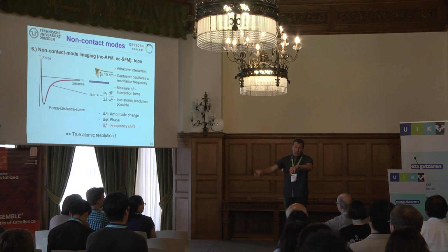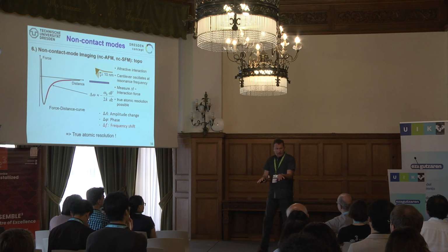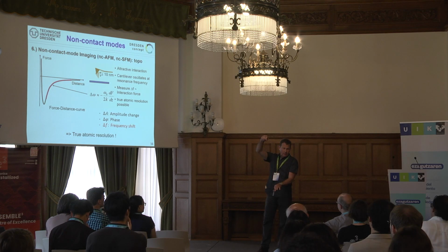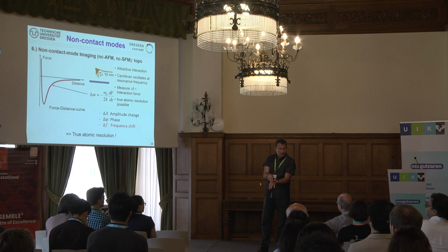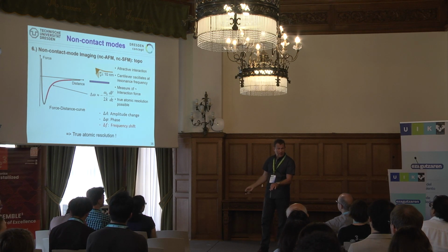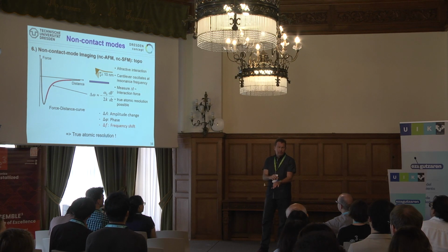Lithium niobate is one where you get an external compensation because there are not too many internal charges there. Now, if you go for vacuum, this is a huge potential, and one of the ways is to use Kelvin to really balance this off. So you go for electrostatic compensation on your cantilever here, we will see that, and then you have fantastic chances to go for atomic resolution.